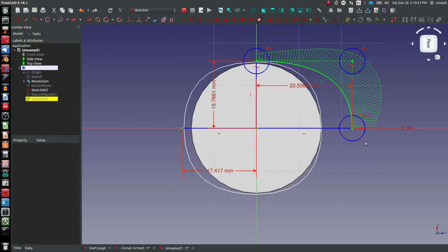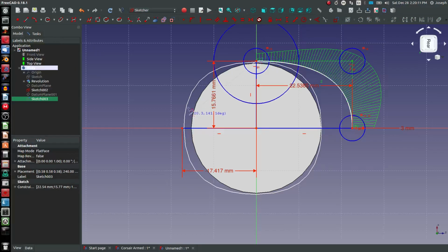And if you're wondering why I'm choosing these relations, it's because this spline, when I choose a vertical from here to here, is going to be tangent to vertical. And from here to here, if these are horizontal, it'll be tangent to horizontal. So we have a smooth transition between 3-point splines that way. Here to here to there.